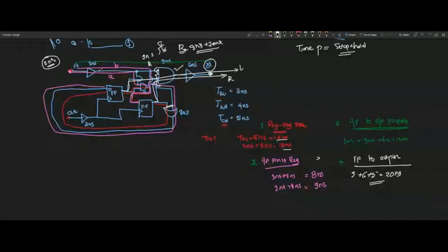While integrating those submodules, you might have used some logic which might be inferred as block RAM. That is one possibility. Then why is it not showing that logic in the report? I can't see where it is taking those extra 12. Can you share the utilization summary, the RPT report of the implementation? I can analyze and let you know where that is happening.